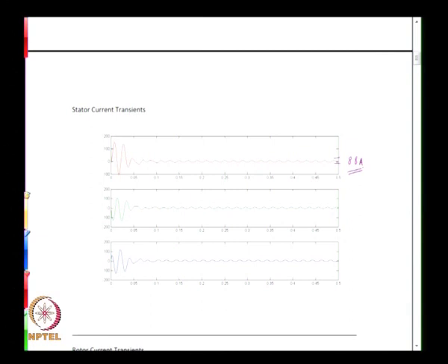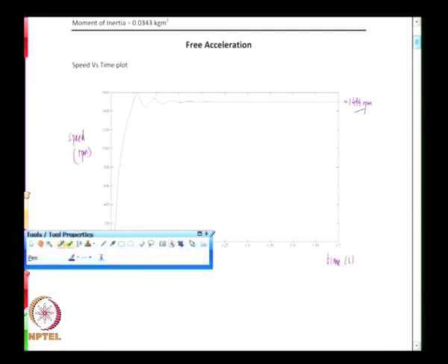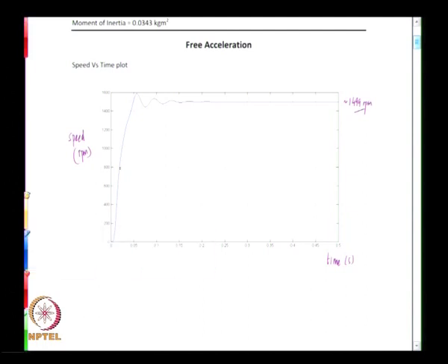From the equivalent circuit it would not be feasible to get how the speed is going to change, that is, if the speed is going to increase in this manner and then oscillate and then settle down, all this information is not available from the equivalent circuit. You can't solve for this situation. What you can get from the equivalent circuit is the performance when the speed has settled down, and you must know the speed at which it has settled down.